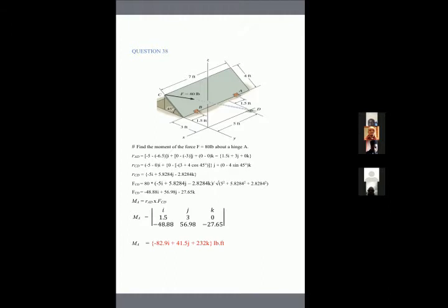So for us to get the unit vector, we need to first get the vector itself, RCD. The vector RCD is simply the coordinates of point D minus the coordinates of point C. So point D, we're working with it even in the previous step, which was RAD.